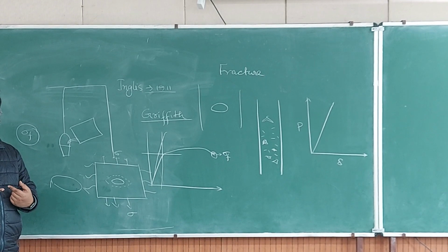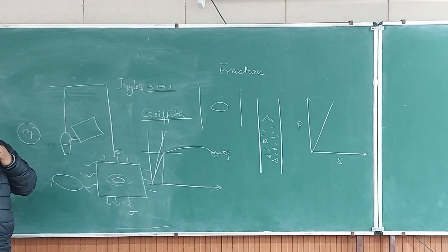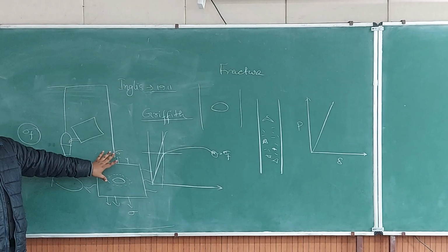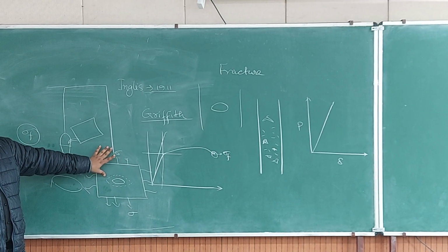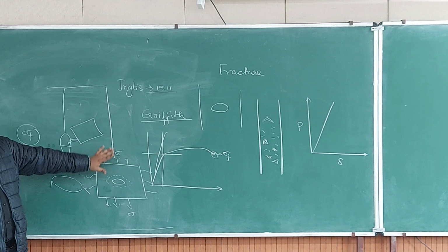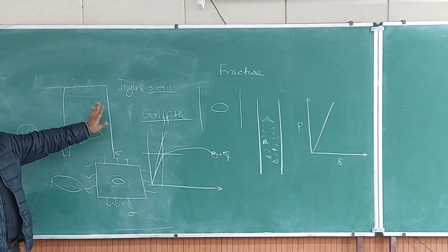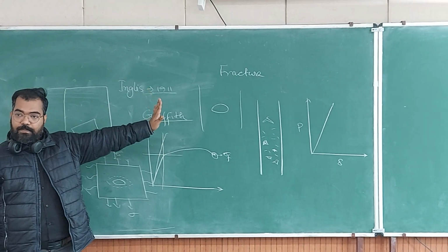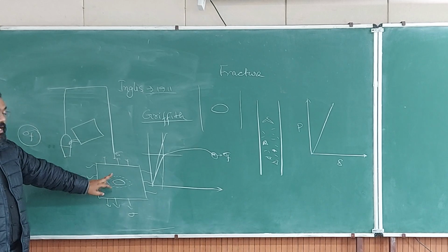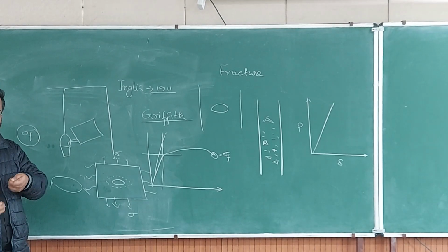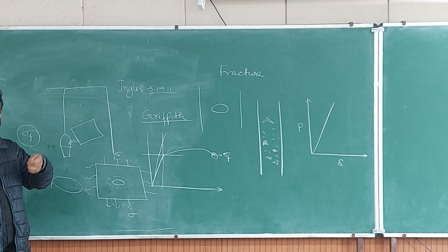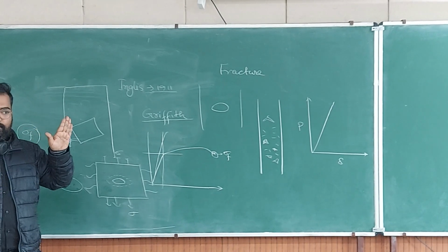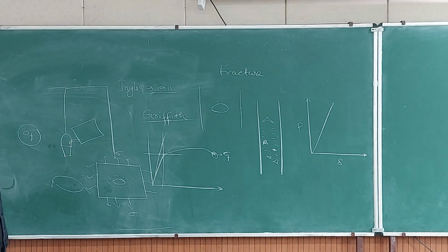You can also imagine displacement control testing. There you are applying displacement on the specimen instead of stress. So you are stretching this specimen increasingly: initially 1 mm, 2 mm, 3 mm. As you increase the displacement, the force also is increasing, right? Then there is a crack growth, but you are not stopping, you are still increasing the displacement. So with crack growth, will the force drop or keep on increasing? This will drop. Why?